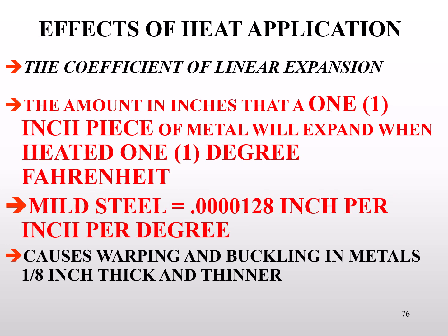If we don't make allowances or take steps before we weld material, because of the linear expansion, we could end up with our materials warping, buckling, or losing our desired gap between our metals. So because of this, we're going to use some methods to counteract this linear expansion or K factor.